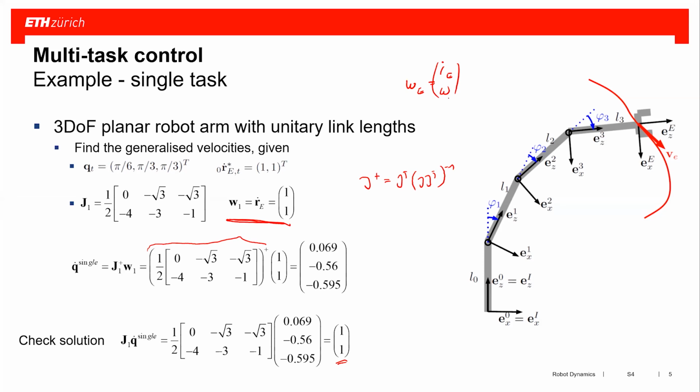And the other way around is if you have many more degrees of freedom that you can modify and fewer tasks that you want to satisfy, then of course you can have different solutions for the problem which make the error become 0. So what the pseudo-inversion takes is the least square minimum solution of that. One is what I wrote here, and the other one is essentially the reverse of that, where you have J transpose J inverted times J.